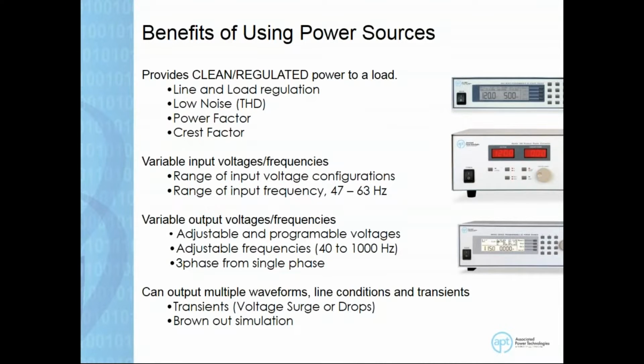Some of the requirements for airplane applications or any kind of avionics applications may be 400 hertz, because the power requirements for those applications may be 400 hertz or 800 hertz. So these are typical benefits you get taking in a 60 hertz input and providing 400 hertz, 800 hertz, up to 1,000 hertz of output from the same supply.